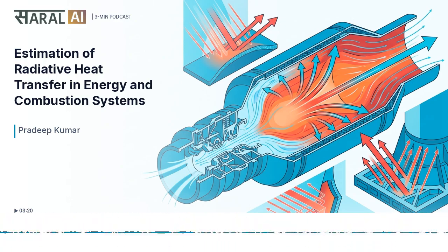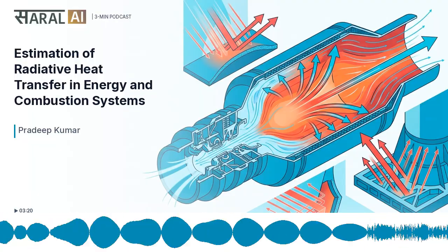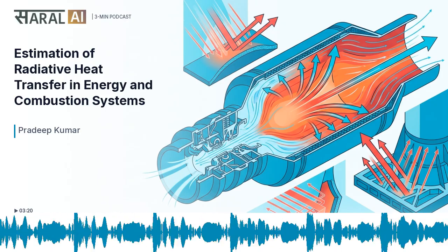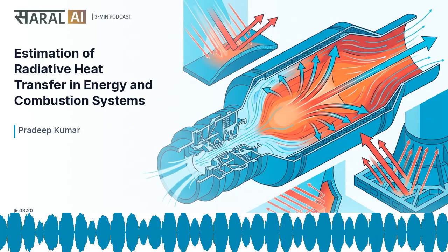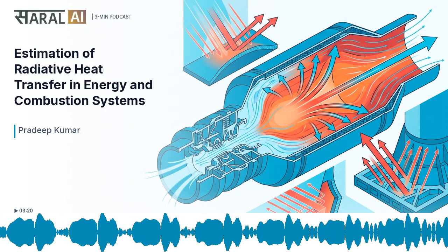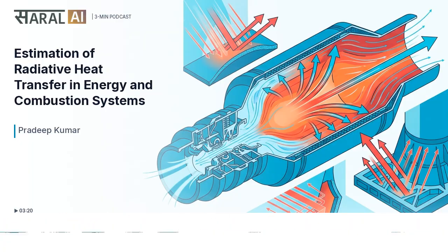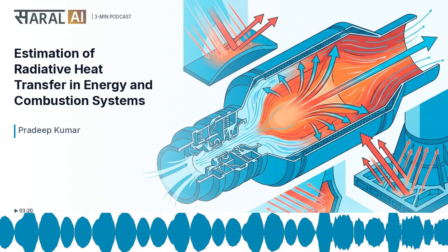A can combustor. Okay. So they're trying to figure out how heat radiates inside this intense environment. Yes, and they compare different radiation models, like Planck mean, WSGG, and SLW models, to see which one works best. Different models for the same phenomenon? That's interesting. Do they give very different results then? They do. The paper shows variations in temperature profiles and heat fluxes depending on the model used.